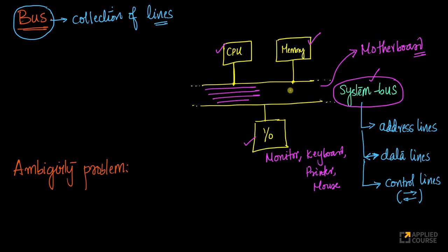The system bus plays a very, very important role because it is used as a highway or a channel. Literally, it's used as a highway through which the CPU communicates to memory, the CPU communicates to I/O, and I/O also communicates to memory, in all of these cases, right? Your system bus itself consists of three types of lines. There are obviously address lines. Remember that address lines are always outgoing, from the CPU, towards the memory or towards I/O devices, right?